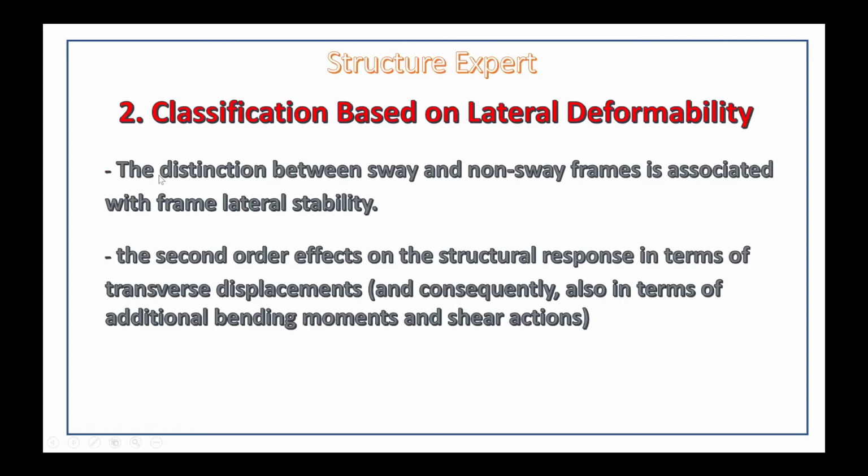Now we will talk about classification based on lateral deformability. The distinction between sway and non-sway, or braced and unbraced frame, is associated with frame lateral stability and the second order effects on the structural response in terms of transverse displacement.